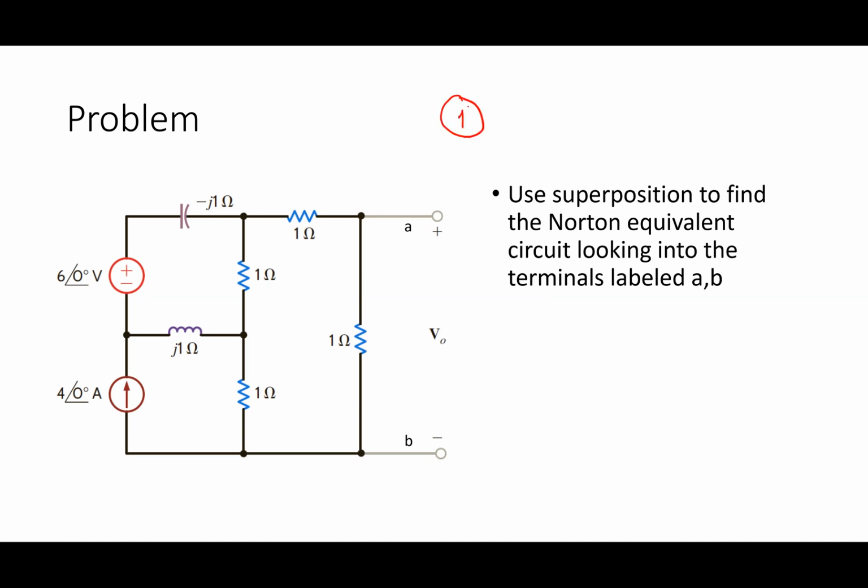Current source in parallel with whatever impedance Z Thevenin I have. And the voltage I would see right there would be the open circuit voltage. What's this current? Well, the current here is 0. But what's that current source? In a Norton equivalent circuit, it's the short circuit current. All right. And the voltage I would measure across the terminals would be the open circuit voltage.